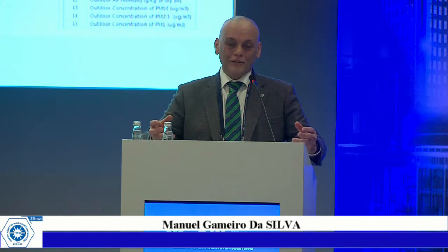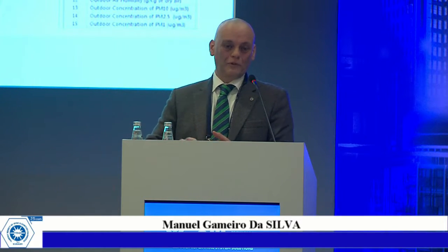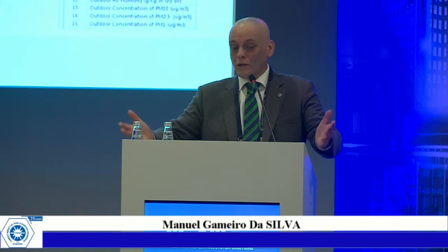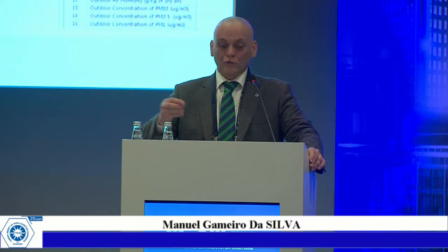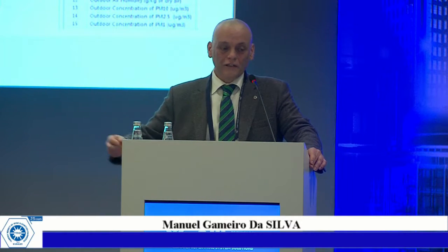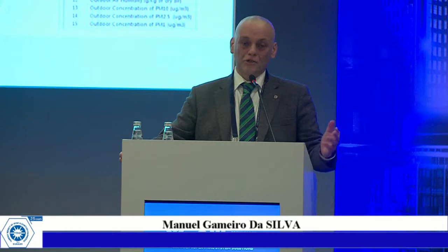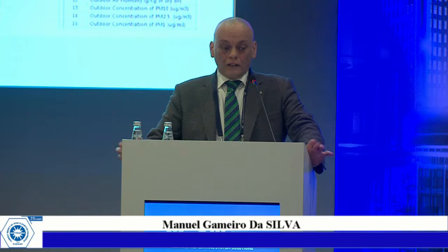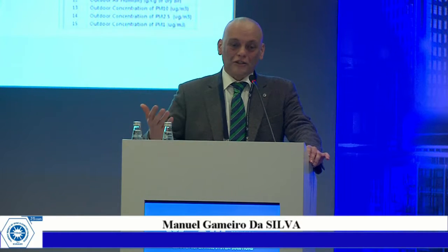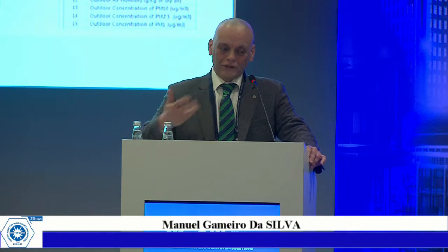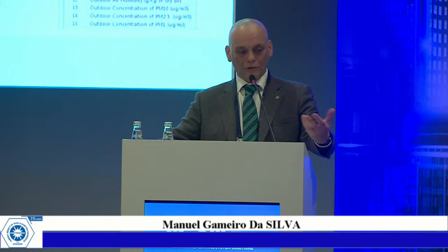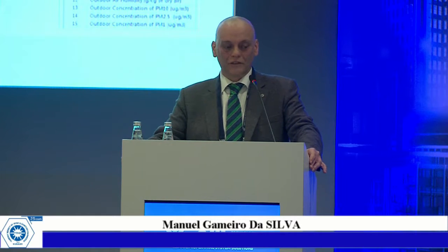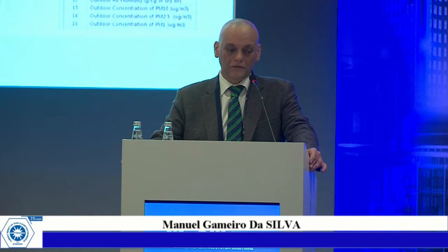So there is a need for some way of measuring the operative temperature in a building. The operative temperature takes into account not only the air temperature, but also the mean radiant temperature and the air velocity. So the initial challenge was to obtain data about the indoor operative temperature.